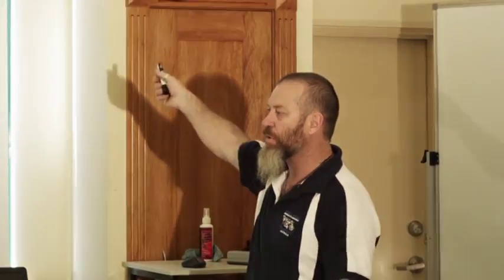And lastly, if you've got a house in the middle of, pick a suburb in the middle of Brisbane, or even in the middle of the Gold Coast over here at Southport, where you've got all these other houses around it, it's full shielding. So that affects the wind classification.